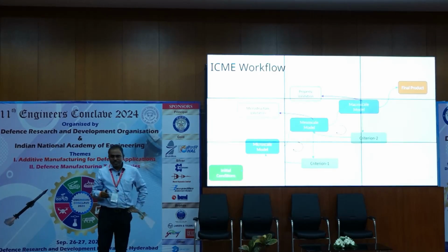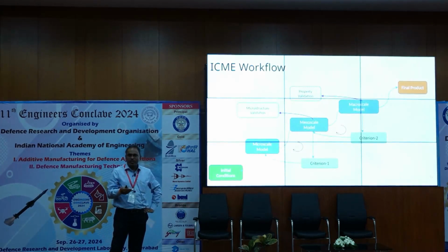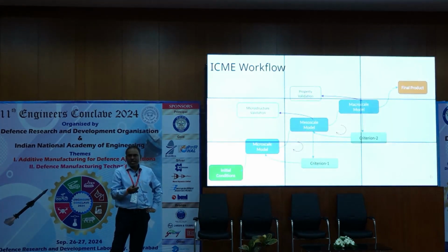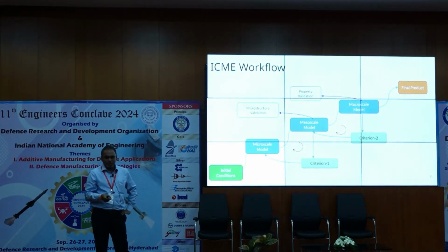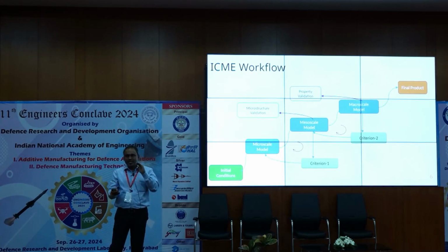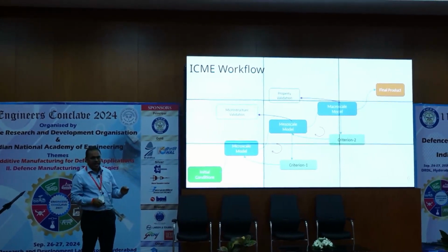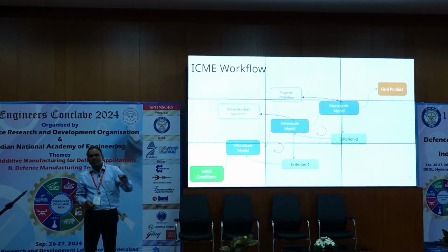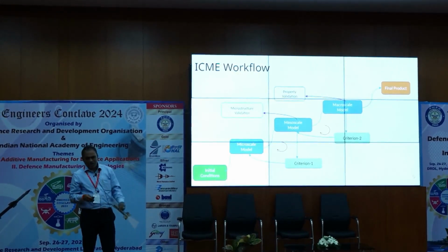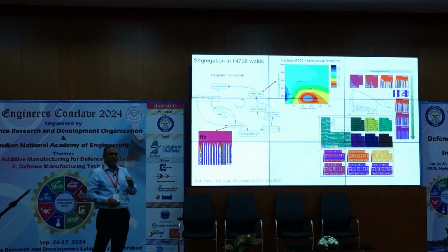So what happens is that you have to frame a workflow of various tools. The information goes from one tool to the next tool, scientifically, so that certain criteria are satisfied. For example, you don't want hot cracking. For example, you want a large window where you could do the heat treatment. So there are certain criteria that you would have, and therefore finally the product can be designed by taking account of all these models. An example for such is also here as a welding approach.